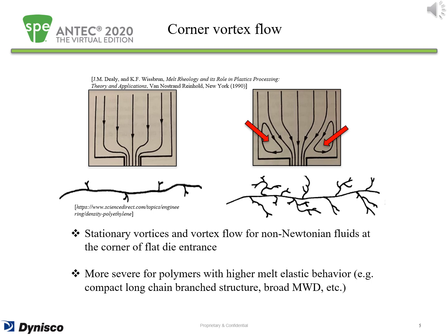The two pictures in this slide show the convergence flow patterns at the entrance to flat capillaries where melt passes through a sudden contraction of channel cross-section. At the entrance to a capillary from a large barrel, streamlines converge rapidly, and this generates a high degree of stretching along streamlines. As you can see in the picture on the left, for Newtonian fluids and for some polymer